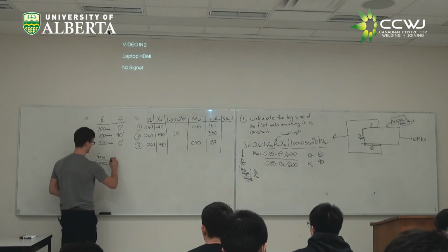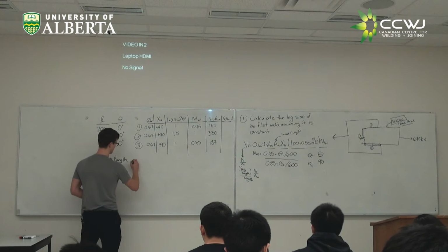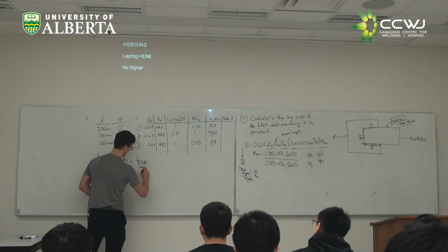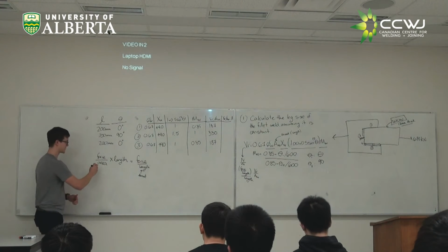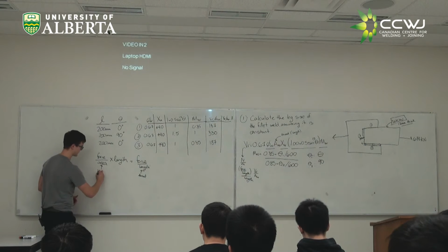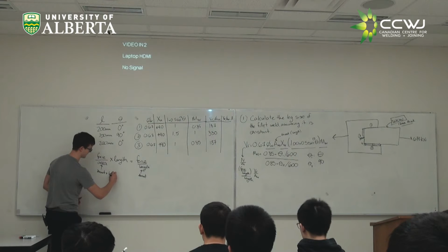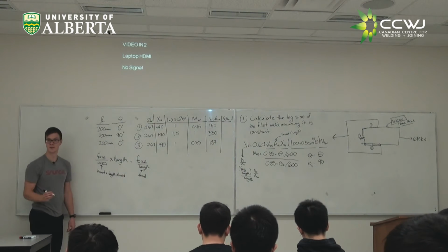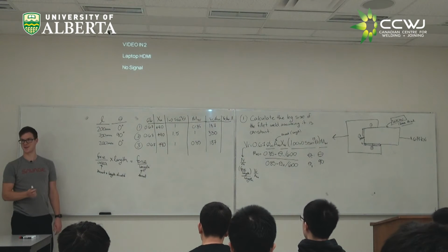And if we multiply our force per area times length, we get a force per length. But this length, this is the throat. So this is a force per area, where area is our throat, times length of weld. So, does this make things clearer or more complicated? Have I lost you guys now?